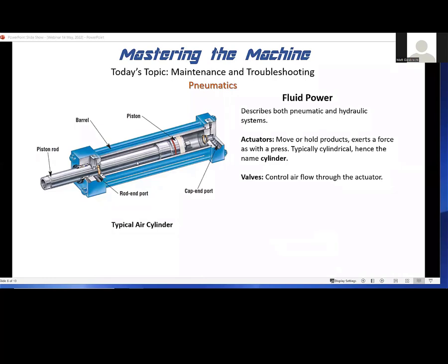Now, when you look at the formula for the amount of pressure that this can exert, you'll see that it's the surface area of this face. Well, from the back end, the surface area is a lot larger than from the front end, right? So if you put pressure in here, you're going to get less force retracting on this cylinder than you do extending from this side, right? Because it is a function of the size of the face.